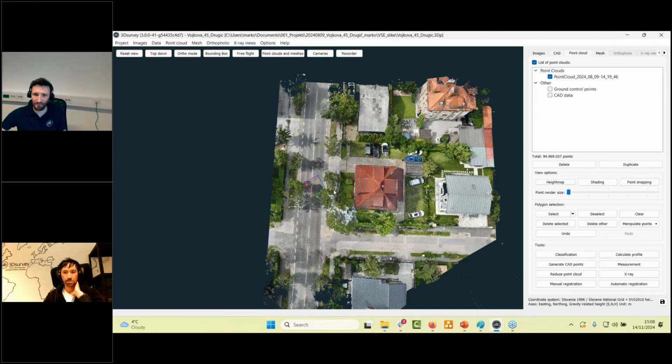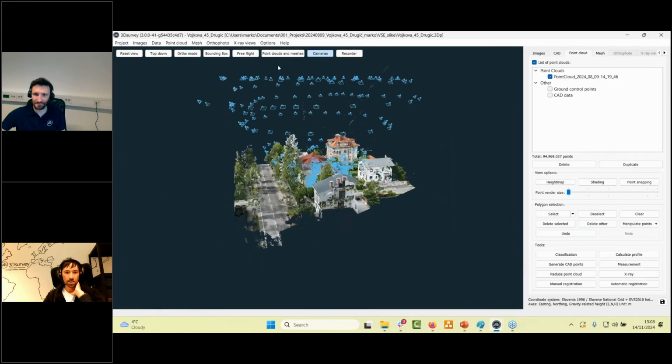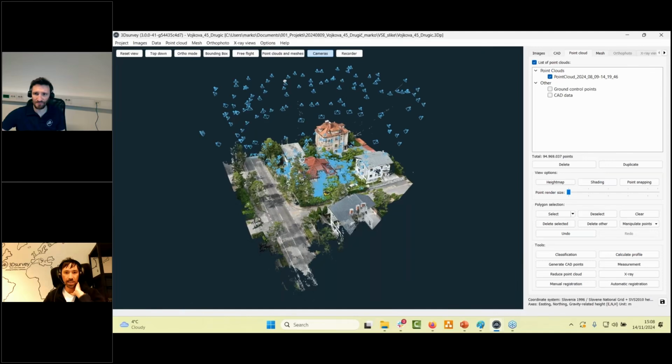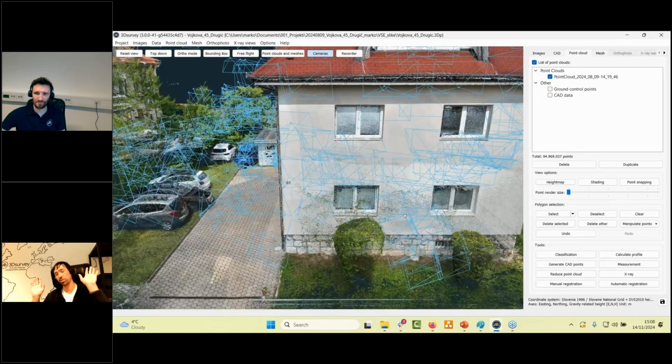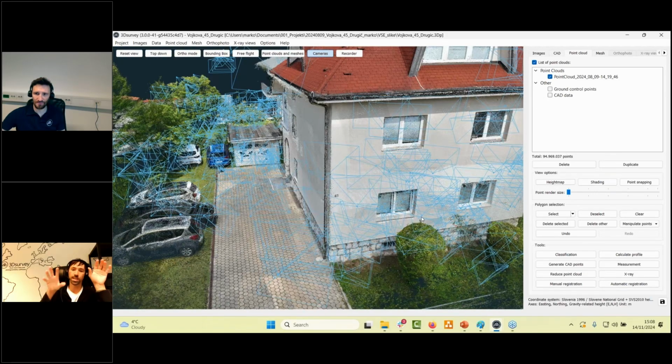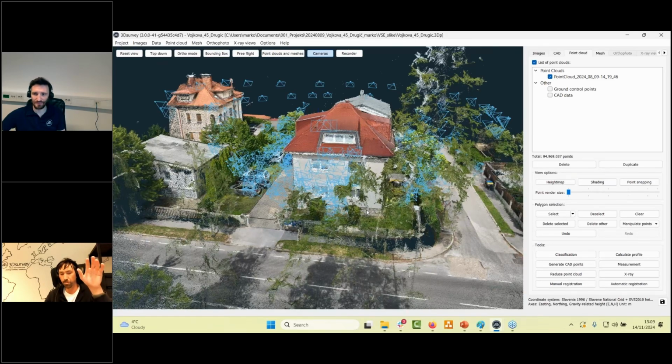Okay, then there's Gunnar. Fine house. Doing the pictures by drone manual, slide below 3 circle. So yeah, Gunnar's asking if it was flown manually. Yes. In this example, just the highest images were captured automatically and everything else was manual. It's safer to fly manually close to the building because the GPS helps you to hold the drone in a stable position. You have time, you can focus. So just for your idea, this model was captured in less than 20 minutes. This is half of the battery and that's it. It's nothing hard, shouldn't be too hard.